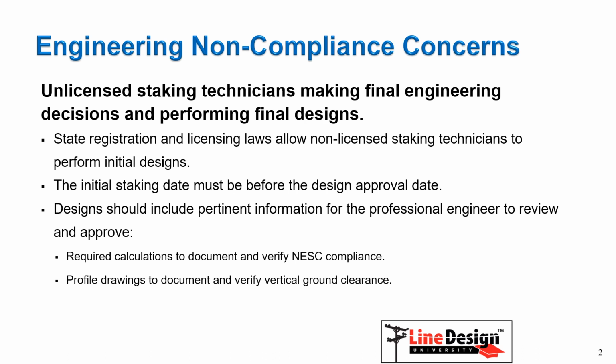Dates on final designs are critical when analyzing engineering compliance. State registration and licensing laws allow unlicensed staking technicians to perform the initial design as long as the initial design is under the direct supervision of a professional engineer. Dates on the final design are important, and the initial design must always be earlier than the engineer's approval date. The initial design must be thorough for the professional engineer to review, which includes all required National Electrical Safety Code calculation results and profile drawings.